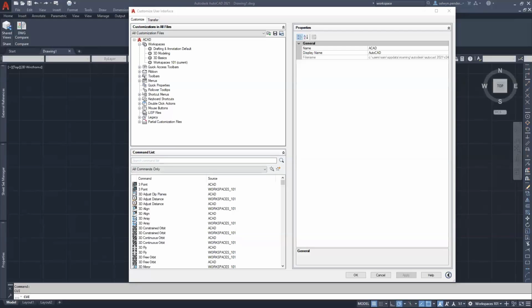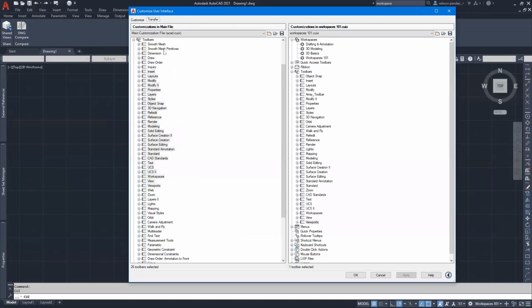So Chris, if you ask that question, you're running Civil 3D. So the process that Selwyn's showing you here is the process to operate with. Yeah, AutoCAD has a migrate from previous release, but Civil 3D doesn't. Hold on, sorry, I'm just looking. Yeah, there's nothing for Civil 3D. No. So yeah, transfer is the way you would go in that situation.